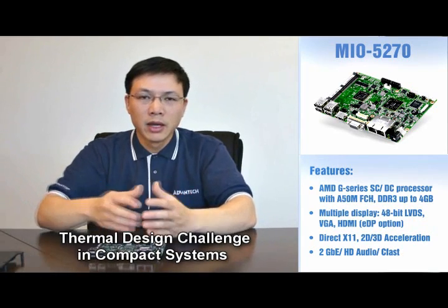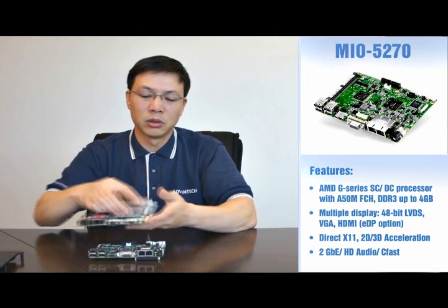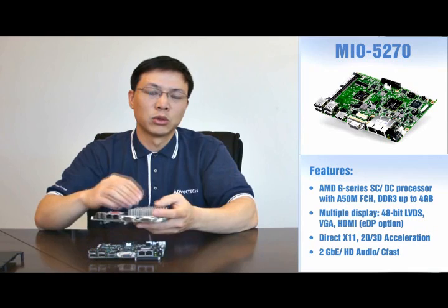For example, a compact chassis with very small airflow, such as modern kiosks where they look nice but they need to remain compact, or within the vehicle where space is limited and the airflow will also be limited, or other more stringent applications such as explosive environments like oil refinery, coal mine, gas pump, or even natural gas refuel station. In this case, there's limited or no airflow, where using a traditional heatsink will be a challenge to transfer the heat outside of the chassis.